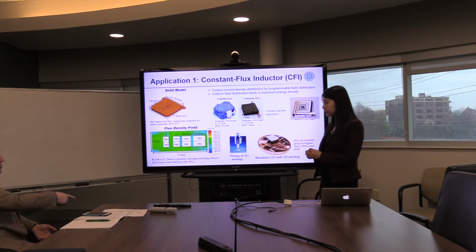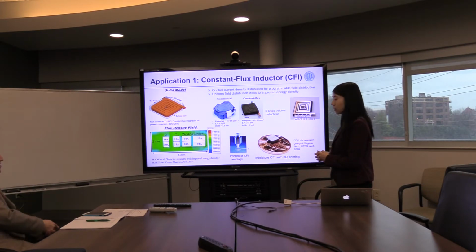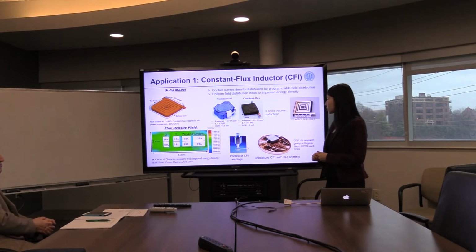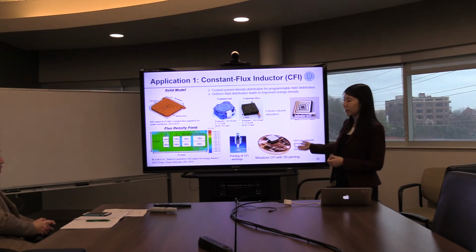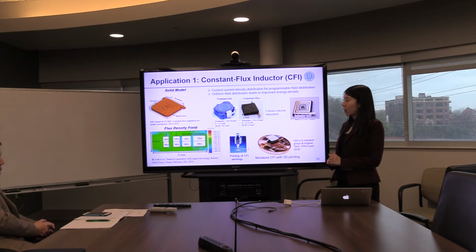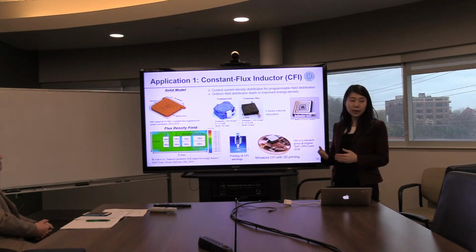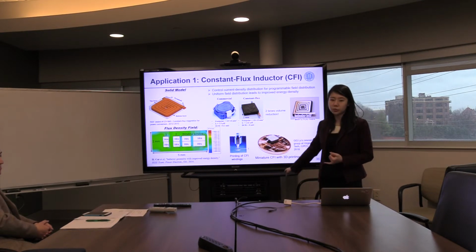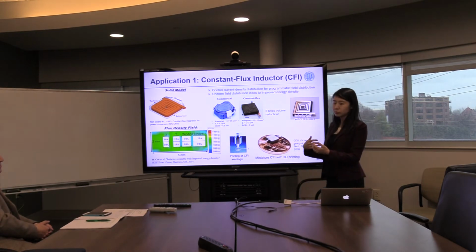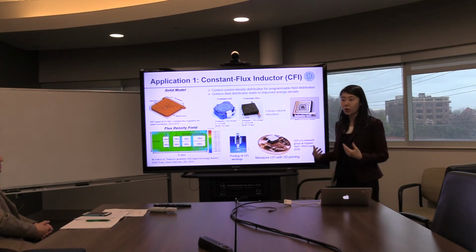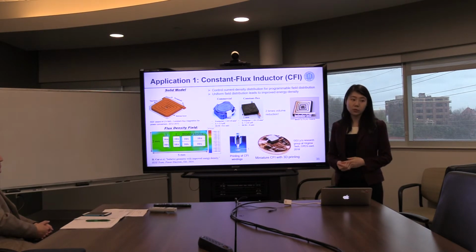Could they use other tools, or even the analytical model you mentioned at the very beginning, to come up with maybe the same design? Well, we can use software like Maxwell to run optimization sweeping methods, but we just sweep a lot of parameters to get the best design. But from our modeling tool, we have the strategy. Not only for uniform field distribution, but for example, if we want to have canceled flux coming through different current density distributions, we're also able to do that with the modeling tools for the field.